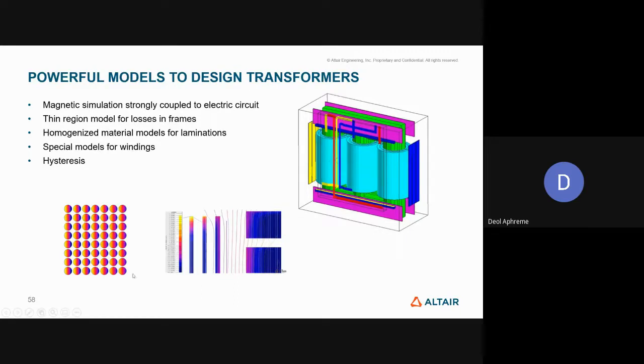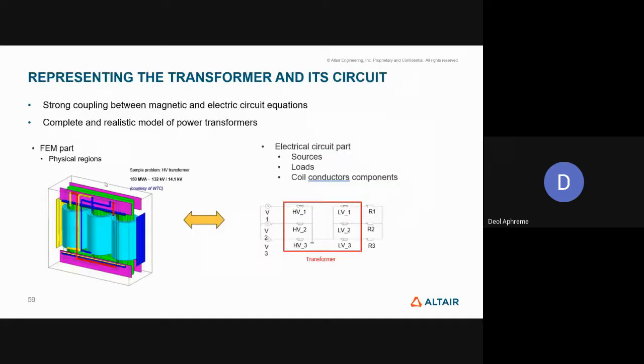So we can definitely simulate them with perfect accuracy, and have at least some basic understanding of what sort of winding is required, what would be the optimal distance to have very little skin and proximity effect, and all these things. And even the homogenized materials, all these things which speak about the characteristics of the transformer.